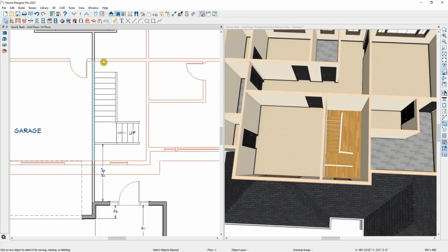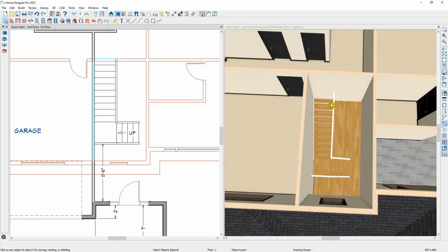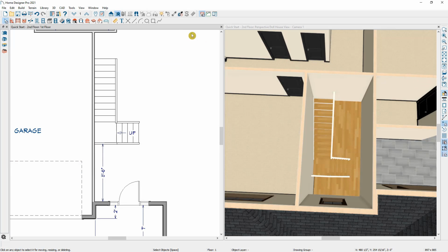And there you can see where that wall is on the second floor. And I'm just going to select our stairwell and then drag the stair section until it's coming up to our reference floor display. And there we know it's positioned correctly. And then we can turn that reference floor display off since we don't need it anymore. And then over in our floor plan view, let's go up to the second floor.